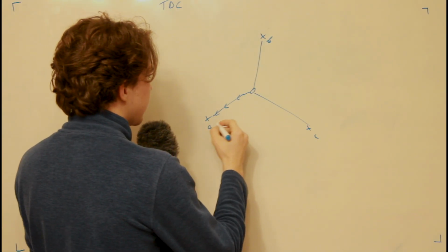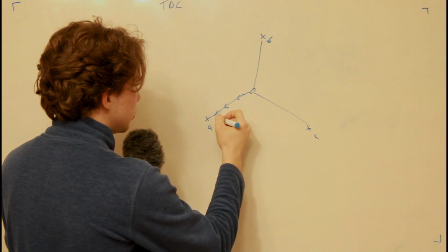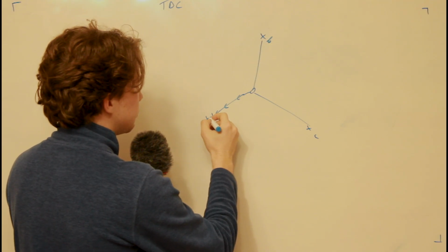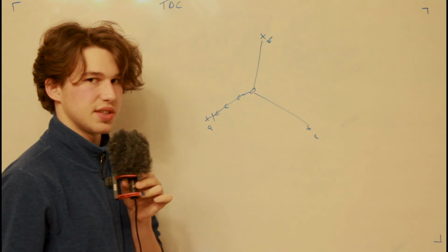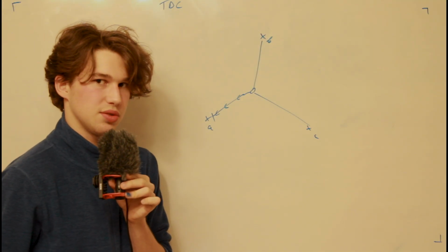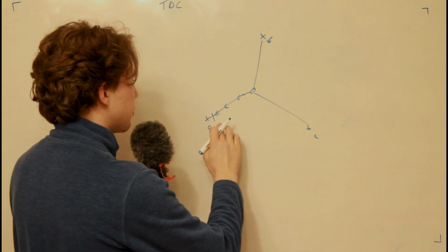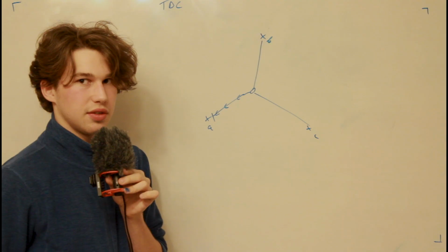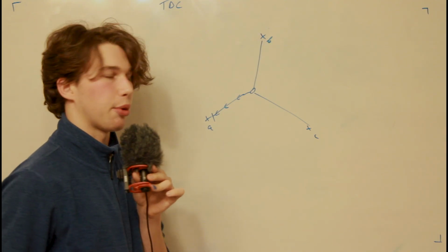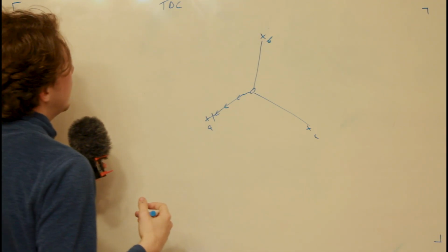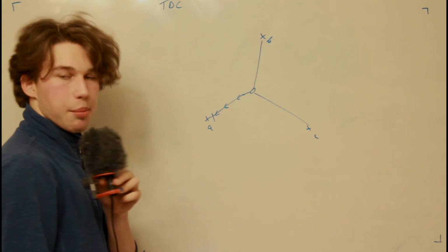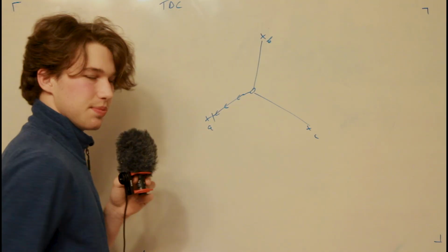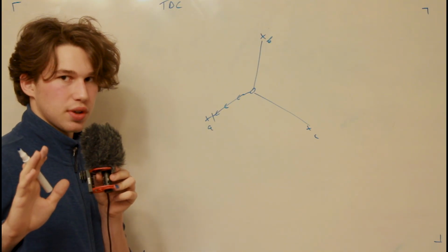And by that, at some point, we will find Floaty at point A. It will be pushed with its bumper. I've added bumpers to Floaty for every motor. Again, the motor starts to experience a very high torque, somewhere near the 0 value, and it knows, I'm at point A. When this happens, the most calibration process is already finished.